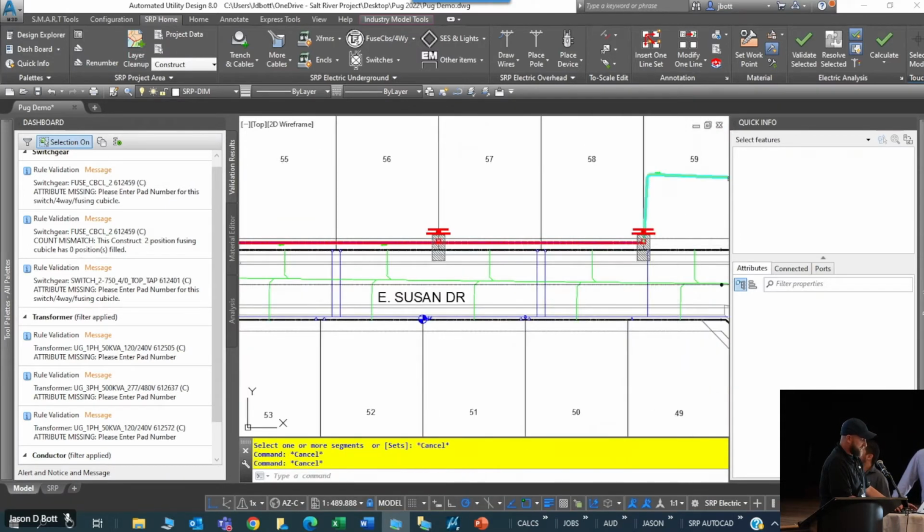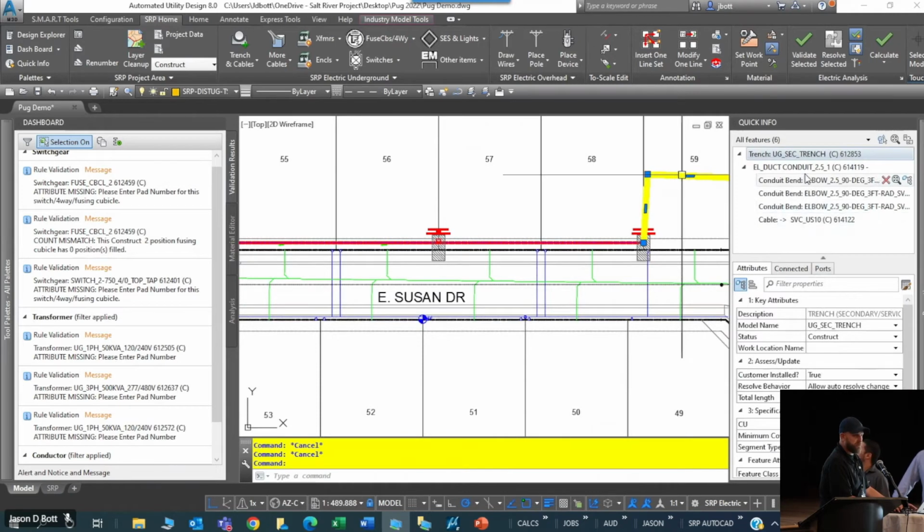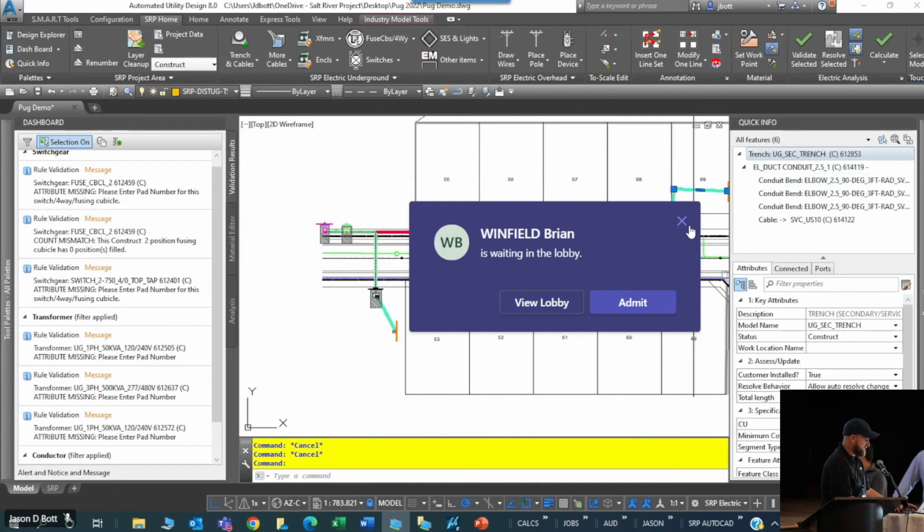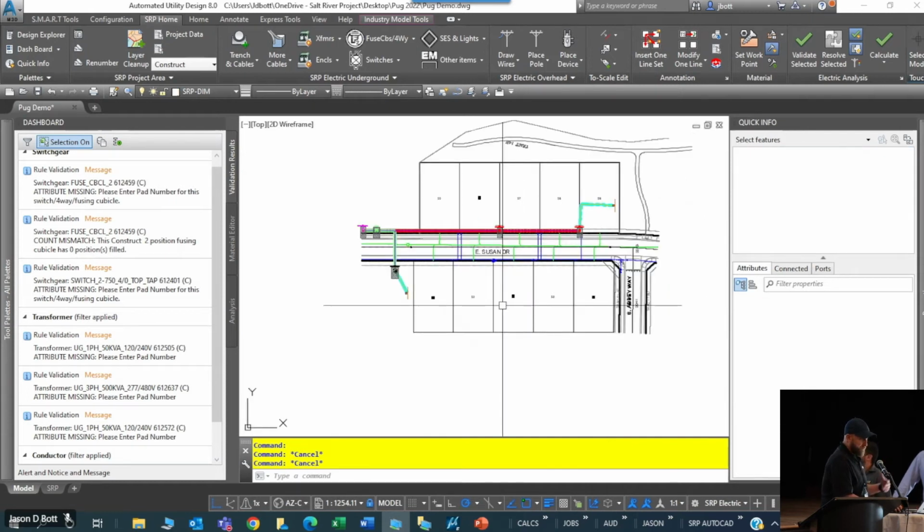So this is different. Obviously, I'm going to get 1/0 here. I'm going to get 2.5-inch conduit. I use the same exact button. It just uses the SES to calculate and looks at our charts and gives it what it actually needs. So this is the model. Once they've done with the model, people ask this all the time, well, how do I see what's going on? Well, there's the expand feature or schematic feature that's built into AUD.